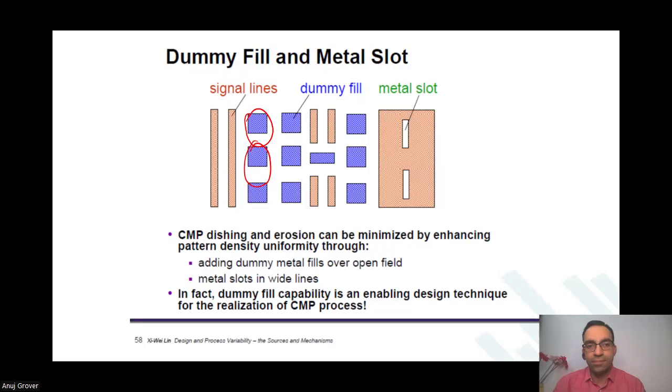So, sir, they will be part of my GDS, but you have not characterized them. I'm not finally able to understand. They will finally become a part of your GDS. But when you designed, you did not know that they will come there. So you did not put them. So the capacitances with which you designed were way lesser than what finally are there. Your system will completely go for a toss.